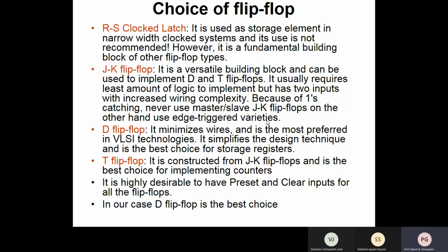D flip-flop is the simplest one. Okay. Its excitation table is also simple. So D flip-flop is mostly used in case of the state machines. Okay. Also in case of the CPLDs and the FPGAs, D flip-flop is used. Okay, so many times you'll see only the D flip-flop. Of course, there can be a multifunctional flip-flop, which can also be configured as a latch over there, but necessarily it works as a D flip-flop.